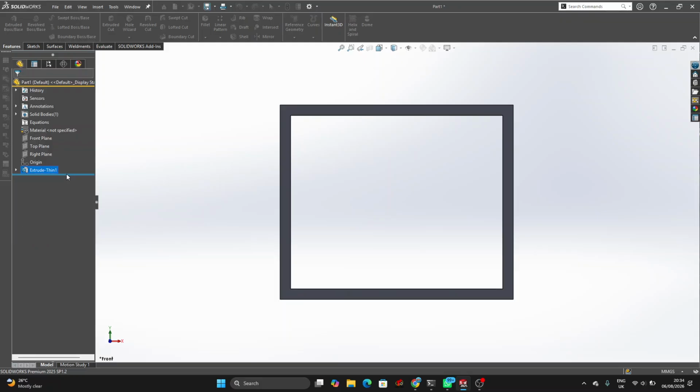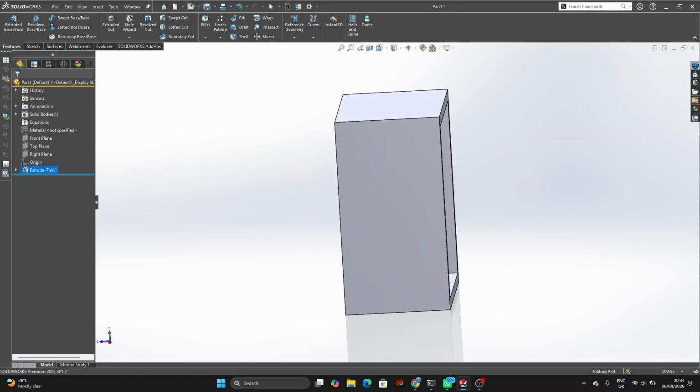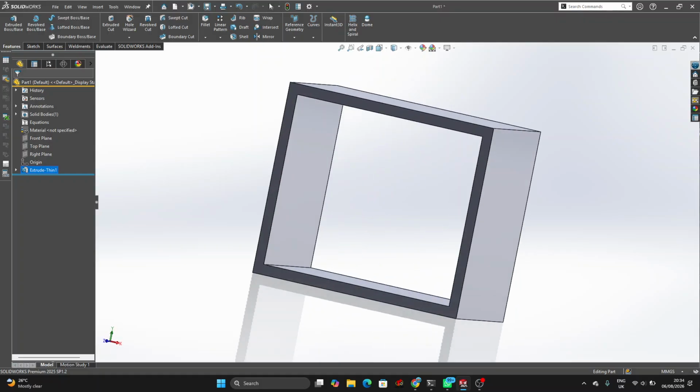You see what the feature does now. Can you see? Actually, it is extruding out. That means it's just extruding the sketch alone. That's what the feature does. Its work is actually similar to an extruded surface in surface modeling. It's similar to it, but it has thickness, unlike extruded surface, that one has zero thickness. So that's what the surface tool does for the normal surface tool.